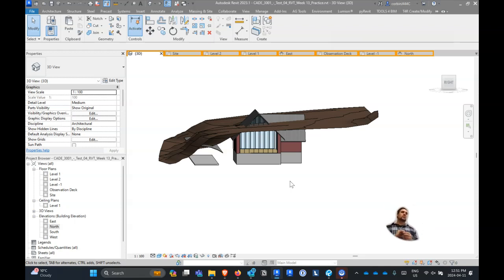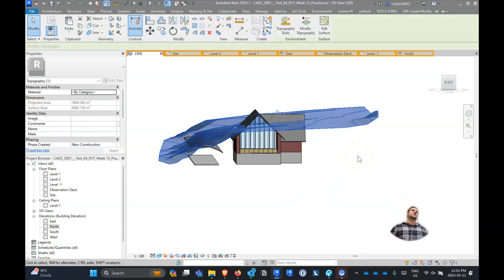One thing that we sometimes do is our site file in a separate Revit file and link it in. Because then when we link it in, we can artificially move it up and down without actually changing our building. I think that's really complicated, and we're not going to go over that today. But that's certainly something you can do if you want to keep the elevation of your topography lines accurate. Does that make sense? Kind of. So when we create the topography in a separate Revit file and link it in, we're not adjusting the elevation, we're just lowering the link. And how those files are linked is separate.